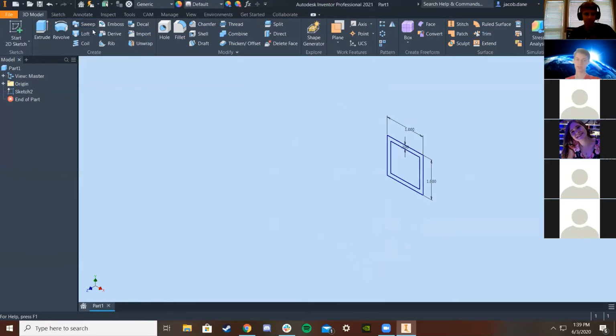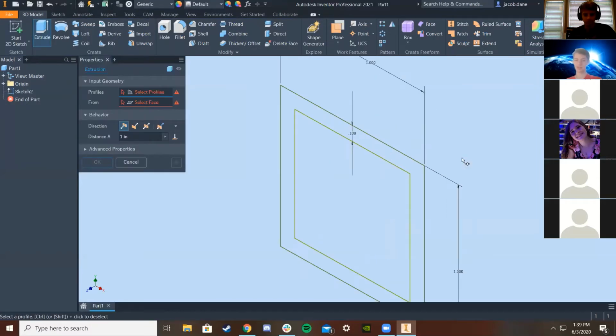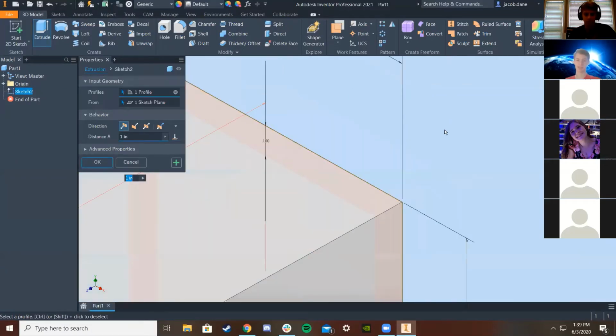There are a lot of different tools that you can use, but one of the base tools that you're going to use in CAD after you make a sketch is just extrude it. This takes a 2D sketch or plane that you made, and you need to figure out which part you want to make and whatever it highlights. So here I found the highlight of exactly what I want to be extruded. I'm going to click that, and then it'll give me this menu on this side.